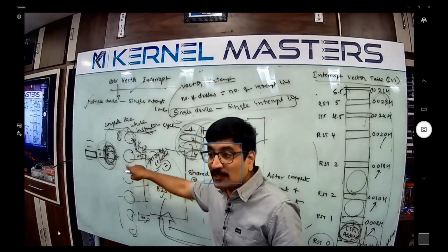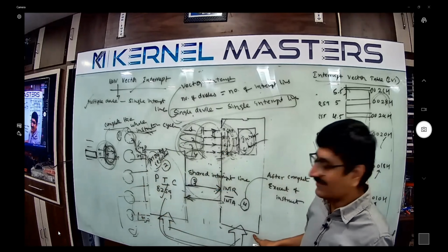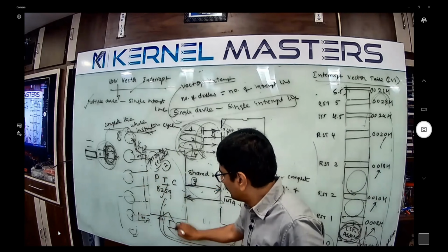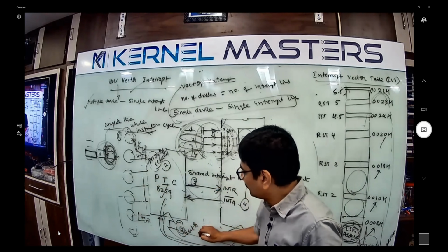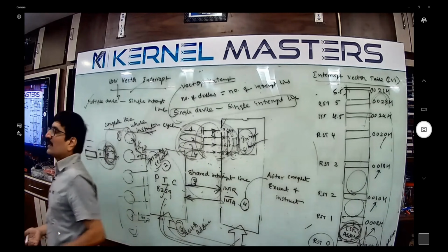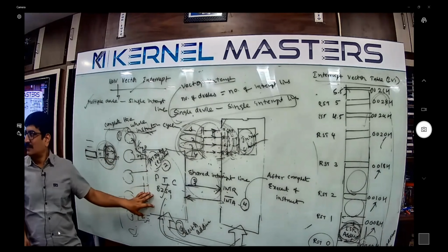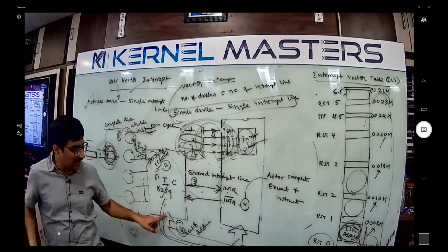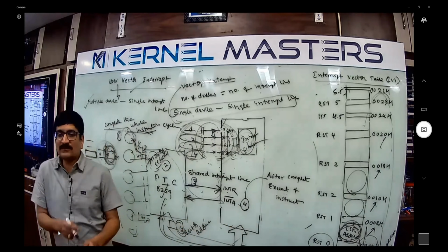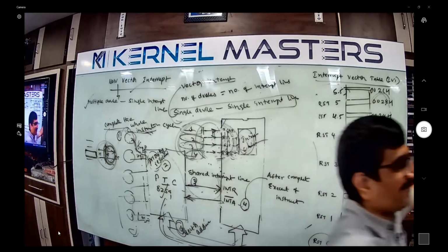The interrupt vector address is sent to the data bus. That is the fifth step. The microprocessor doesn't know where to go, but the PIC knows the address. So in the fifth step the PIC sends the vector address to the microprocessor. The microprocessor reaches the vector address and understands: okay, I want to go here. You can go now to that position.